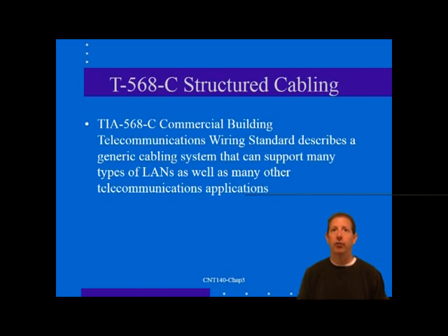However, a few cable plans offered wide connectivity to both voice and data. Out of those plans, a universal cabling system finally emerged: the EIA-568, now revised as 568C. Now, it is widely agreed that the flexibility and utility of the standard EIA-568C system offers the best alternative for new installations. The standard can be used in lieu of the proprietary cabling systems with little difference in performance. It can easily support a wide variety of LAN topologies and offers growth to 100 meg and then beyond.